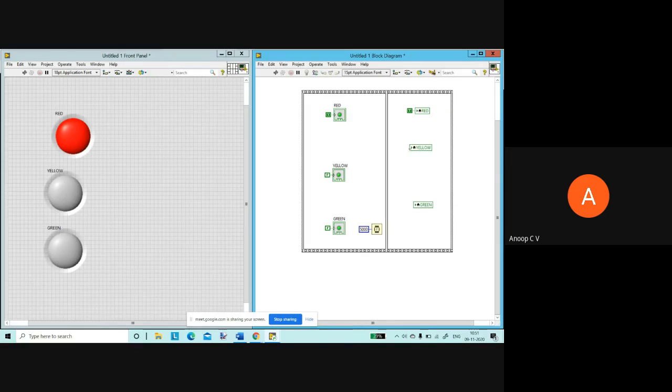To create a constant, here again create constant, here again create constant. So now in this case what should happen is red should be off, yellow should be on, and green should be off. And maybe this delay I can copy paste, not a problem. Delay modules, I'll just copy paste this delay part. We can give a 4-second delay, or 3-second delay. 3-second delay we'll give.